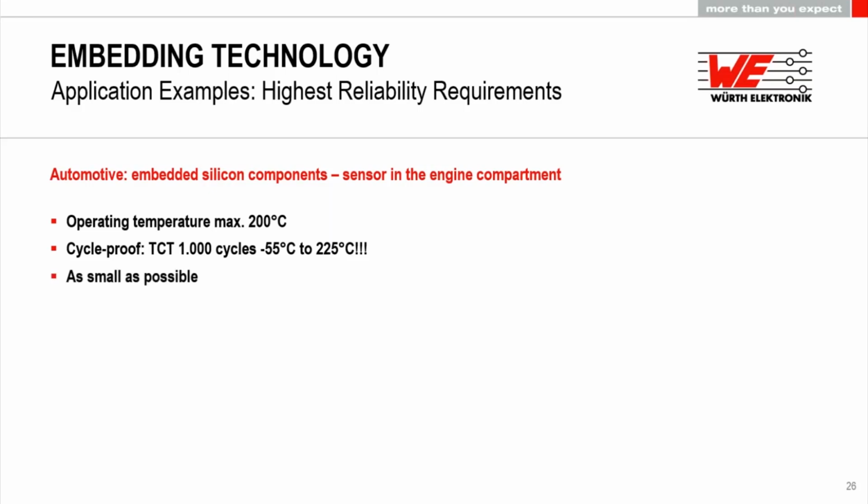It should have been as small as possible, but still, it should be able to be used in an injection molding process. Why do I mention this? Because these two last points conflict with each other. The smaller it gets, the more the module might be affected by the pressures being used in the injection molding. Therefore, we needed to find a way in a build-up how to still make it very small, but find a way that it's not being bent or distorted during the injection molding.